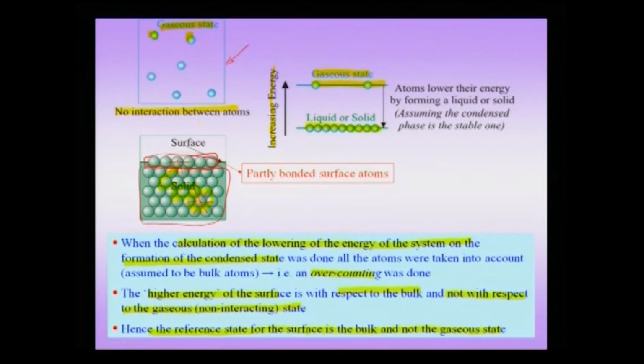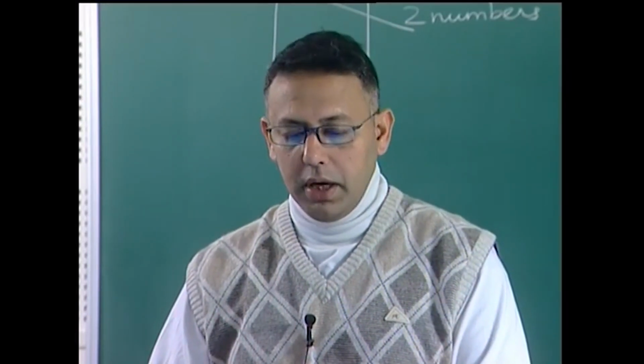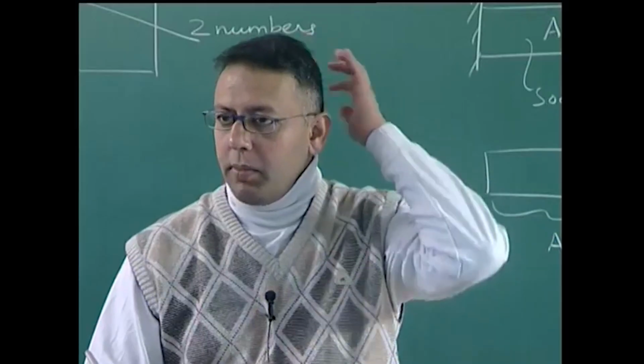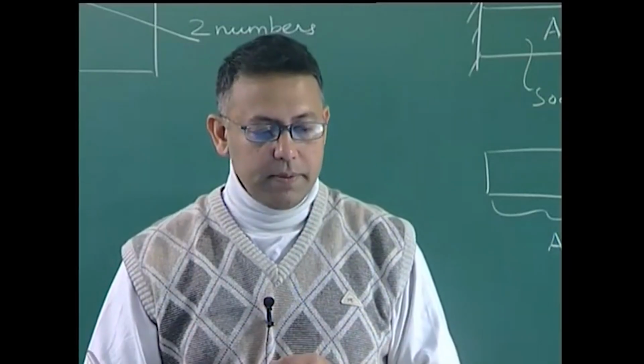So, let me summarize some of the concepts so far. Surface energy is not an energy in itself, it is an energy which comes because of overcounting, and when I am talking about surface energy, I am actually talking about the reference state being the fully bonded state or the bulk crystalline state. Of course, it need not be a crystalline state, it can be an amorphous state or a liquid, but for simplicity we consider a bulk crystalline state.